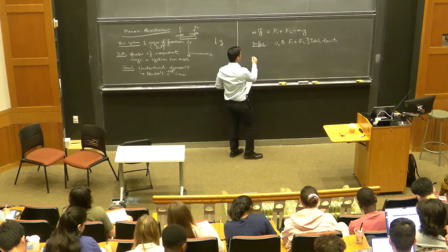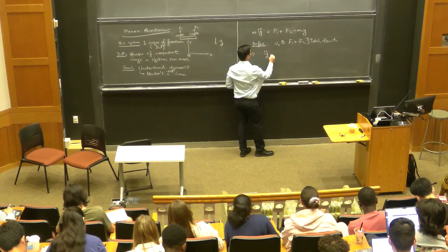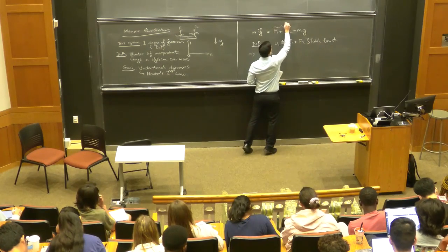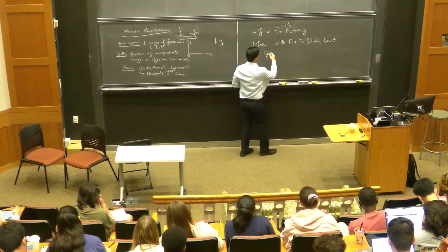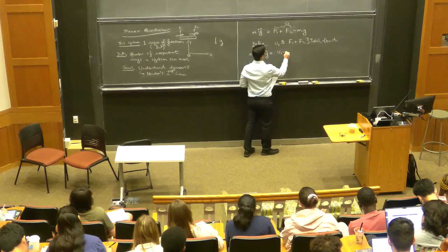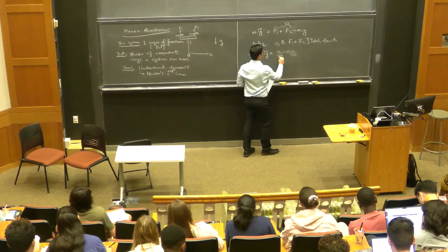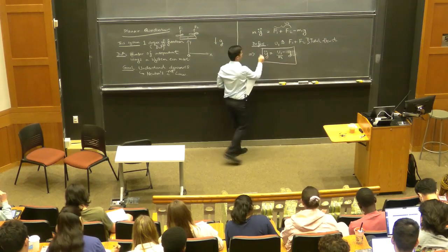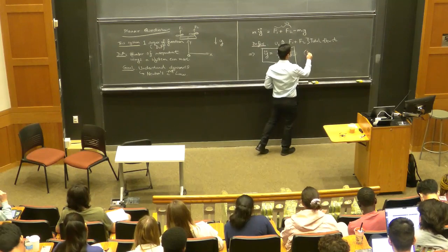So we can rewrite this equation that we have. We can put y double dot on the left hand side, F1 plus F2. We're going to call this U1 just to make the equation slightly more compact, and because we'll use this notation later as well. So U1 minus mg, or I can write it as U1 divided by m minus g. Okay, and I'll label this as equation 1.